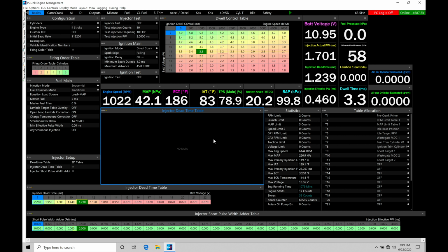And when we switch over from our low to high cam operation, we need to properly characterize the additional fuel and spark timing delivery based on that high cam operation. On the high cam, we're going to have higher lift and more duration. As a result, we're going to be moving more air into the engine, so we're going to need more fuel, and we need to have a separate table to be able to add additional fuel in.